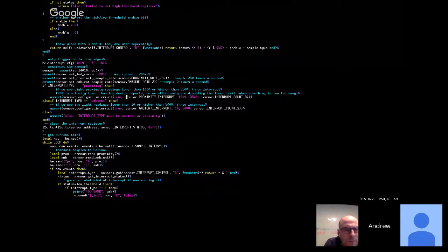So we say turn on interrupts. We want to interrupt on the proximity if it's lower than 1,000, which it will never report a value that low, it seems to floor out at about 2,000. I don't know what units of proximity it gives me. It may just be some kind of infrared absorption. It may actually be the amount of infrared light it sees bouncing back. 3,500 is about half an inch. So again, we don't have a real scale for this.